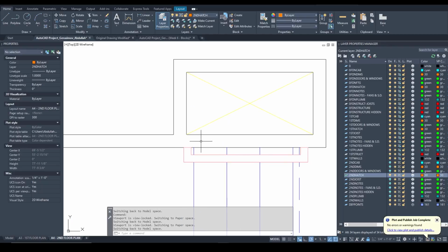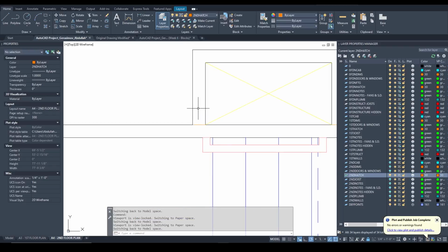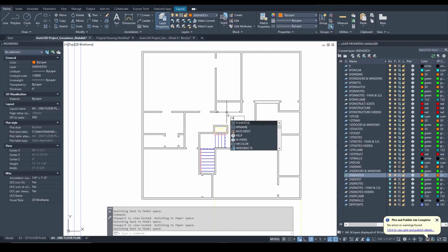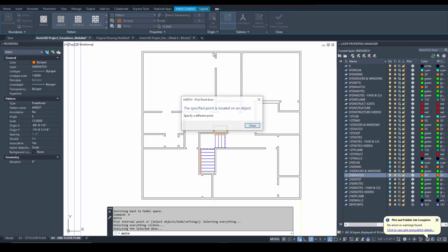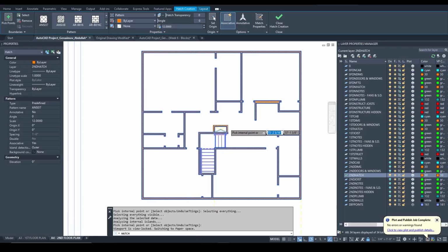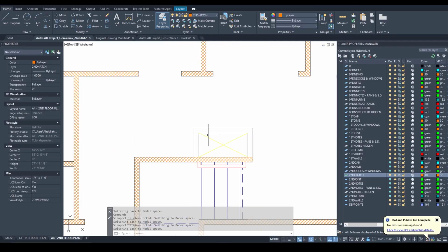The way you can mitigate this issue is staying in the same layer, second hatch, type in L for line, and try to isolate the portion potentially where that hatch is having an issue. So I drew 2 lines essentially blocking an opportunity for a hatch to go this way as well as this way. So let's try this again. H for hatch. Go inside of the cavity. There you go. Now the area that I blocked off was actually the area that apparently was problematic, and that